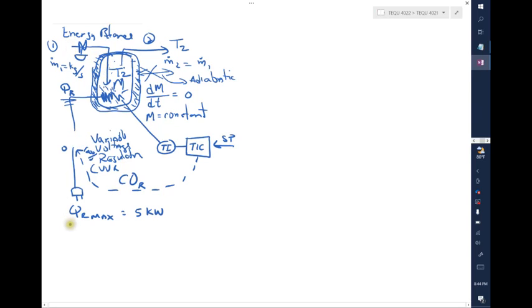The same happens here also with the amount of mass getting into the vessel. That amount of mass, I can write it here, and let's say that M1 maximum is about 0.126 kilograms per second. So if you make the math a little bit, this is about 2 gallons per minute, typically at a home. That's the volumetric flow, 2 gallons per minute. In mass flow, which is better for this energy balance, it is better to have it in kilograms per second.